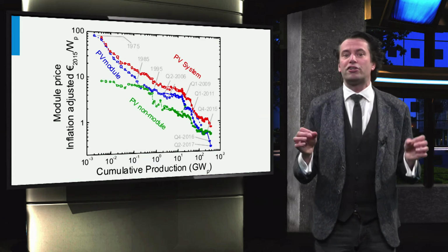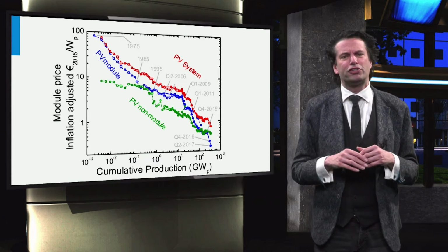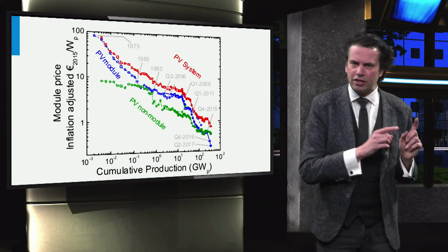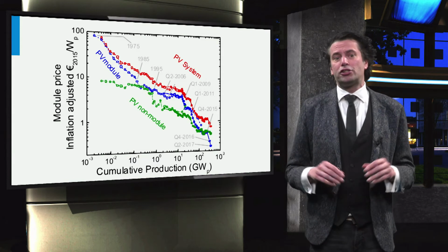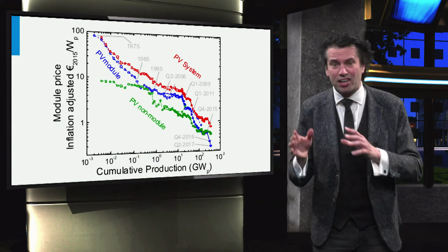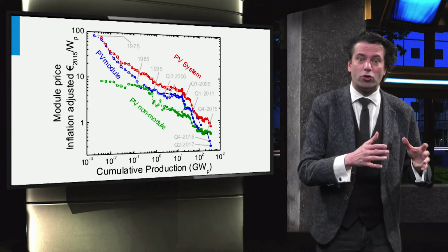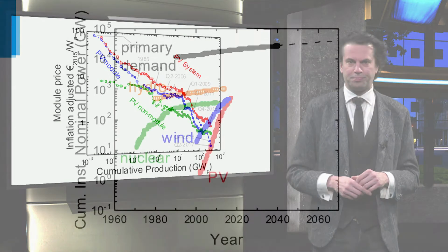This shows the advantage of the crystalline silicon PV technology, which has a higher module efficiency ranging from 16 to 20% in reference to the thin film PV technologies. Higher conversion efficiencies mean higher yields per area. While the non-modular costs per area are the same, the cost price per watt peak of the non-modular cost will be consequently lower for modules with higher conversion efficiencies.